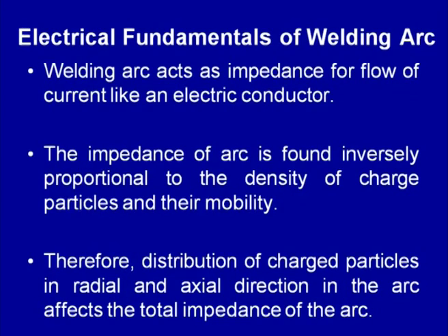and accordingly for a given flow of current the generation of heat will also be uniform. But it has been observed that the distribution of the charged particles in the radial and axial directions in the welding arc is not uniform, and accordingly the impedance varies along the length from the electrode tip to the workpiece and from the center of the arc to the outer surface of the arc. And therefore, because of the variation in distribution of the charged particles in radial and axial directions, impedance is affected, which in turn affects the heat generation in the different zones, varying from the electrode tip to the workpiece or from the center of the arc to the outer surface of the arc,